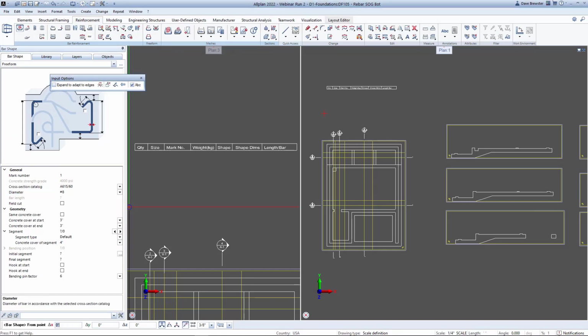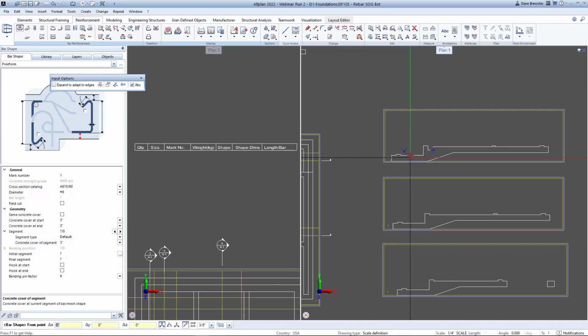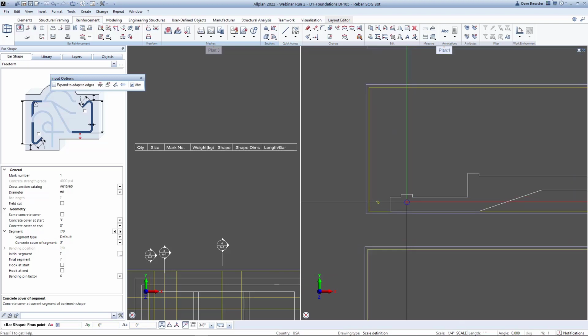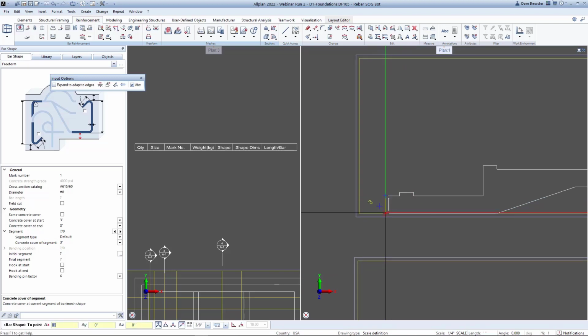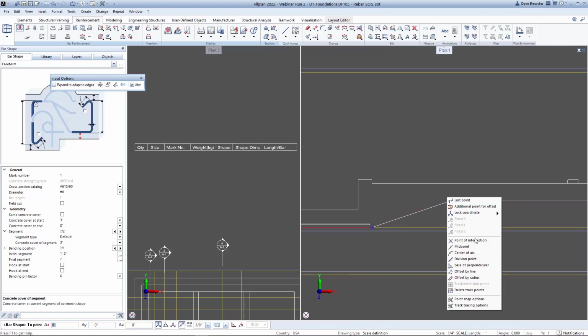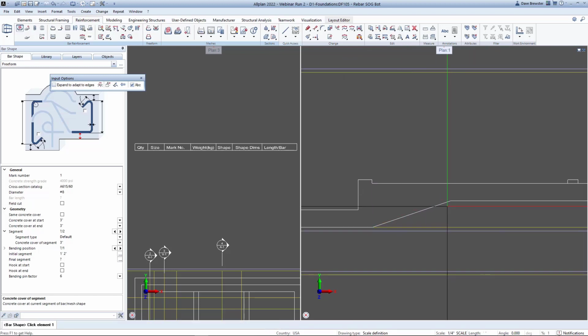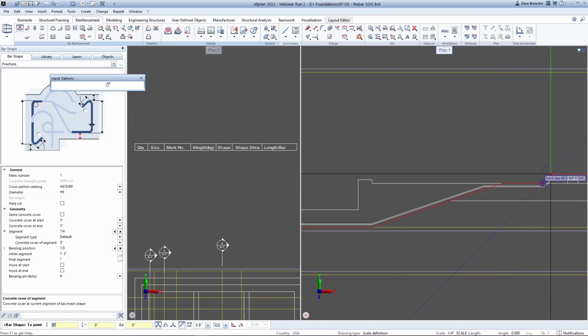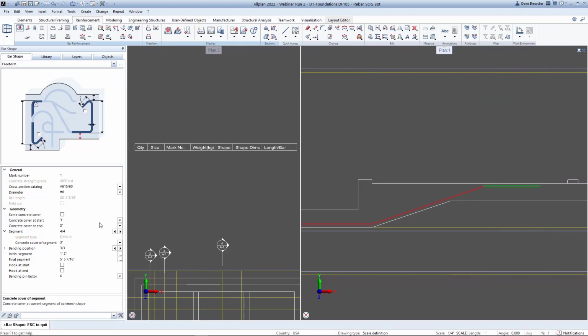We're going to go ahead and pop some rebar in, and one of the biggest tools we have for rebar, we have predefined ties, we have predefined information, but this freeform rebar tool is probably the best tool for putting in rebar. We call it freeform because, as I said earlier, you don't need to pick a shape. You draw the shape, let ALLPLAN tell you what shape you just drew according to the loaded catalog. Now, the catalogs can be different. It can be edited, it can be changed, it can be project specific, it can be office specific.